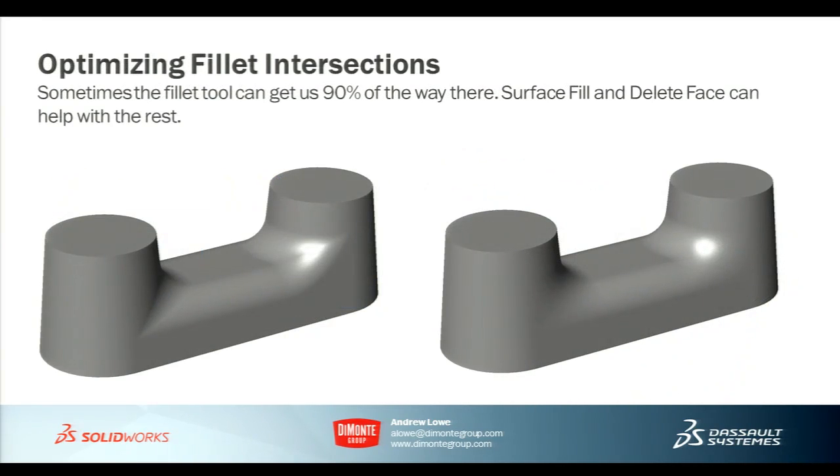So sometimes the fillet tool can get us almost what we need and get us a lot of the fillets, but we might want to optimize some of the fillet intersections. On the model on the left, I've only used the fillet tool, and you can clearly see the fillet faces. Here's a fillet face, here's a fillet face, here's a fillet face. Whereas on the model on the right, I've used the delete face and fill tool to create some smoother transitions at the corner.